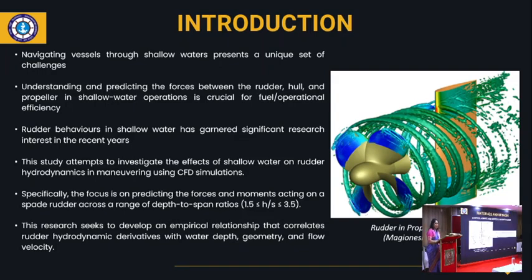So if we look at the hydrodynamics of the rudder, we have this typical maneuvering problem where maneuvering forces are developed, and we all know that in maneuvering we follow a north-east-down system, and the rudder rotation, which is a clockwise rotation, is considered positive. For every positive rotation of the rudder there is a hydrodynamic pressure created.